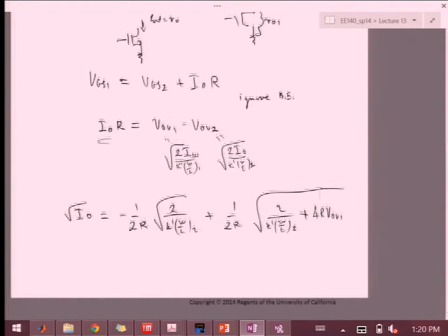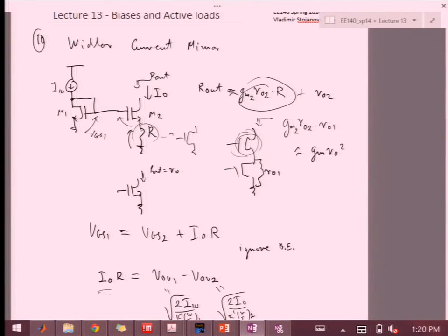So maybe you're wondering why is this interesting compared to the regular source? Well, the reason is exactly this difference over here. What this allows me to do is, because I have this voltage drop on R, suppress the amount of overdrive that I'm giving to M2 for a given VGS1. That means that I'm choking the output current intentionally.